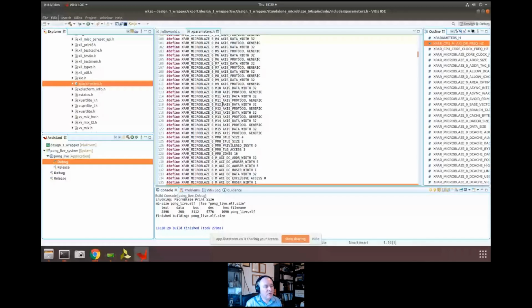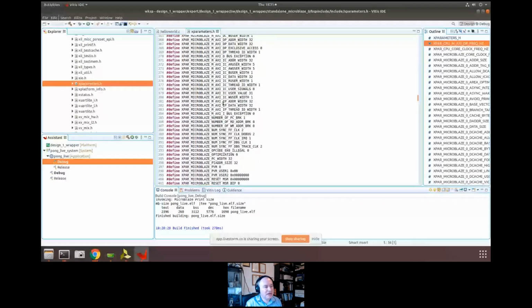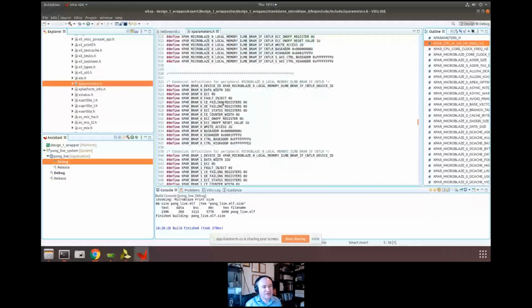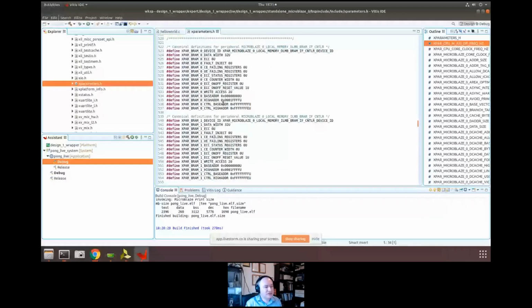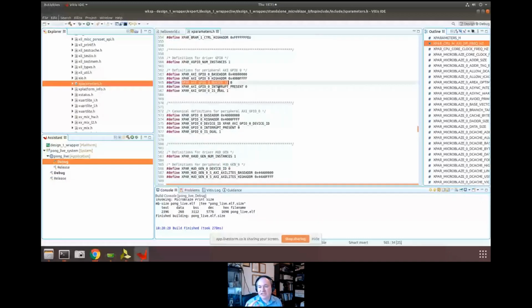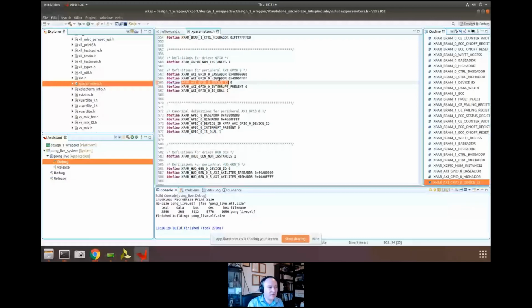But where it gets really interesting is down the bottom, where you can see the additional parameters that we've added in there. You can see, for example, the GPIO driver that we've added, and the name of the beginning address, the end address, the device ID. This device ID is critical to use when we want to actually access that and work with that. So we need to include this xparameters.h to include that design, these device IDs and this entire description of the system when it's all compiled.